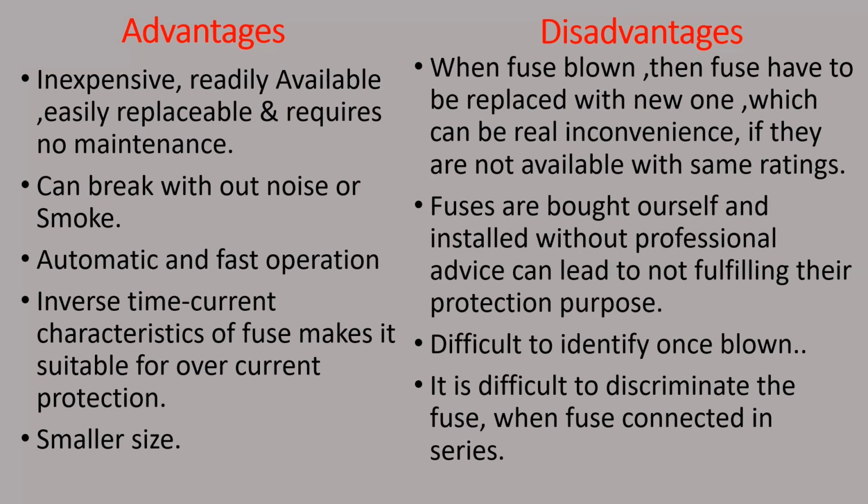These fuses are made of ceramic material, and inside we have some powder to quench the arc, so no flame or arcing will come out. The arc gets quenched by itself inside. We have two metal caps, one at each end. HRC fuses are mostly used for industrial purposes.